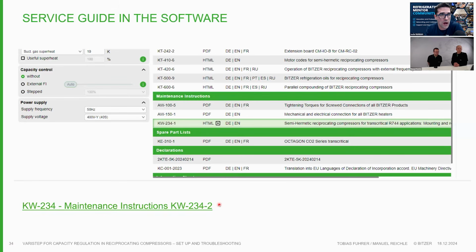So I would bring the system into kind of stable conditions. A little bit higher suction pressure is maybe better than too low. If I run the system at stable conditions, I would take the solenoid coils off the compressor. Of course, we discussed this earlier before the call. We should take care that we don't overheat the coils, so we should put a screwdriver in or disconnect the coils from the plug.